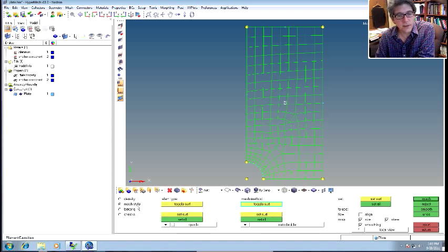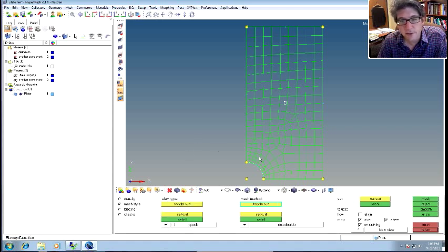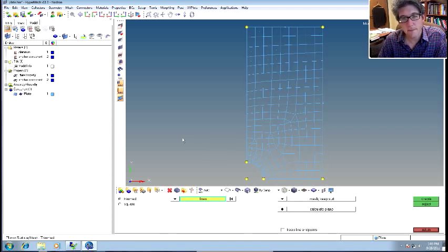It's actually quite powerful. You can also have it generate just quadrilaterals, mixed quadrilateral and triangles, or only triangles. The way this is set is it's set to mixed. What it's doing is using quadrilaterals when it can, but sometimes the quadrilaterals will be excessively distorted, so it uses triangles to help get you a better mesh in the sense of low distortion. Okay, that's good enough. I think we'll leave it at that.